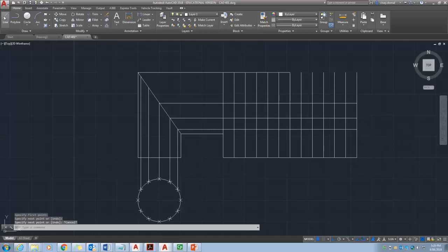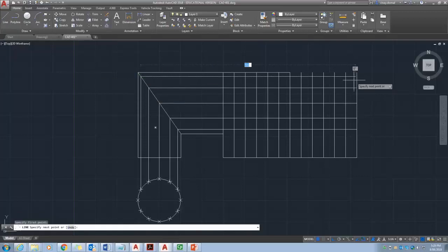Keep extending the lines until it snaps to perpendicularity. Press escape, snap again, find the perpendicular intersection. This should be fine as well. So you can extend this one as well, the bottom one. Once you extend, you can apply the spline, which is SPL. Enter SPL, snap the points and keep joining the points.